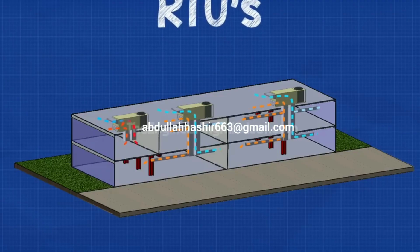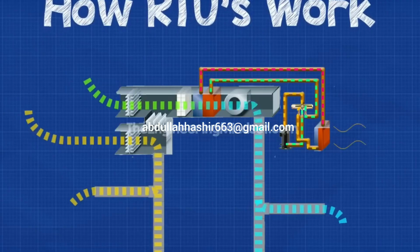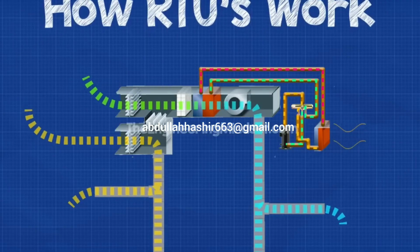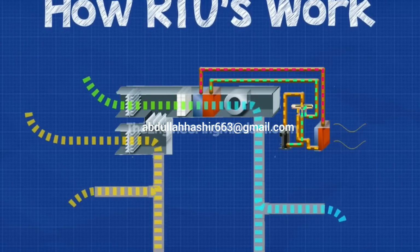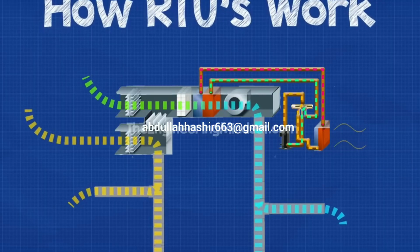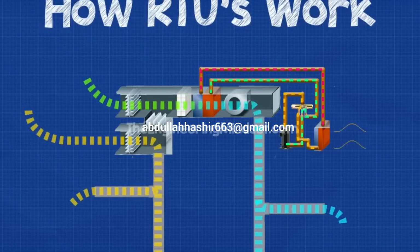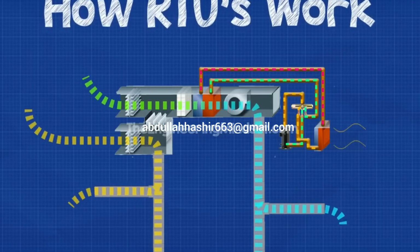RTUs typically have their own inbuilt refrigeration system to provide cooling only, but they can also contain a heat source such as a gas-fired heater or an all-electric heat pump. RTUs house all the components within the rooftop unit. This contains a number of dampers to control the flow of air and can allow air recirculation if conditions are right. The unit will also contain filters to clean the air, as well as heating and cooling coils and at least one central fan. The refrigeration system is also connected to the back or the side of the unit, and this is used to control the temperature.